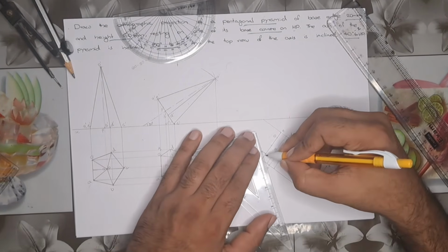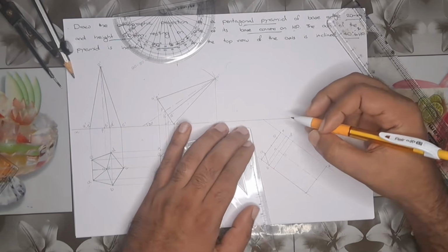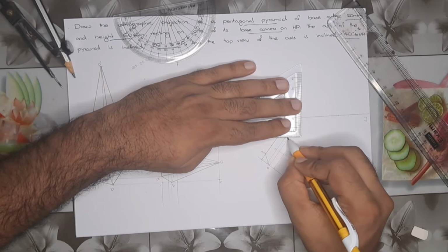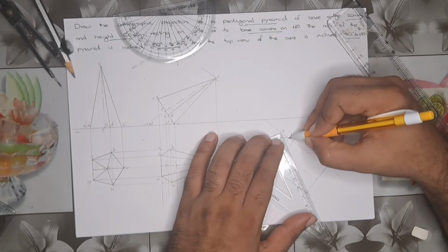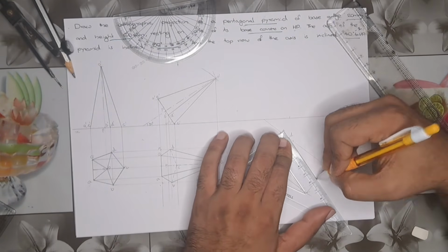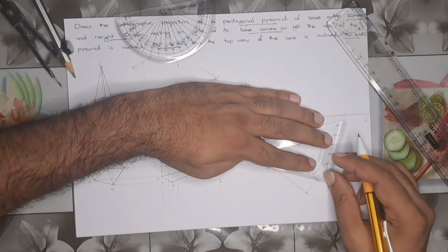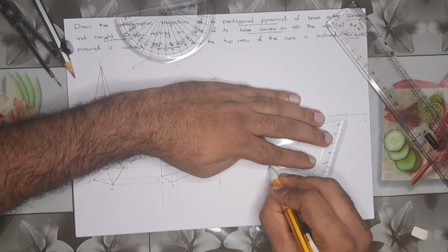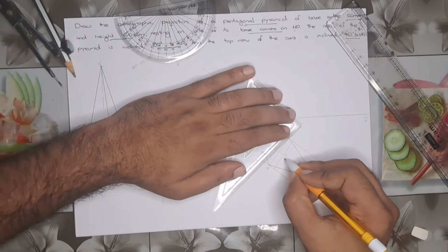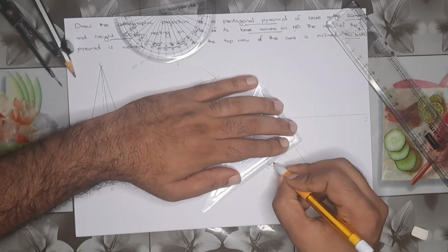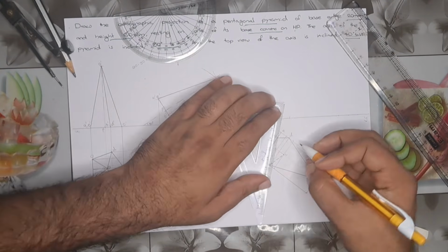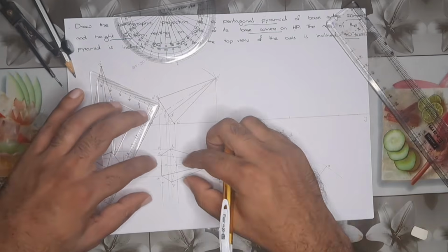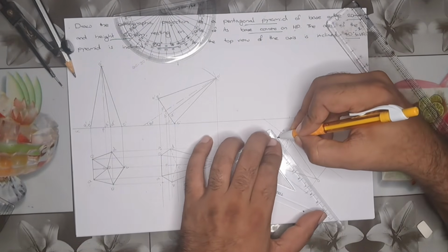So now we have to draw the outer lines just like before. The line ED, then BO. So this is O and BO. Then connect it to C with dashed lines. So a dashed line is used for the hidden edges. We are just copying this figure to here and connecting the remaining parts.